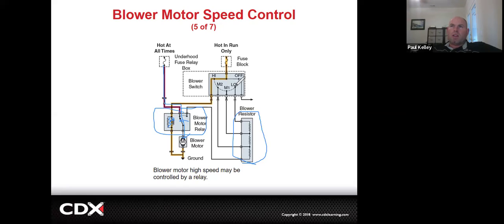It's possible you have an issue here, here, and here, but why would you have 3 problems all happening? It's not likely. You've got an issue in here, and then those will all be dead until you hit full speed. I wouldn't even go crazy on the diag on that. I would say actually, as soon as I jump in the car and it only works on some speeds, I got it pretty well diagnosed.